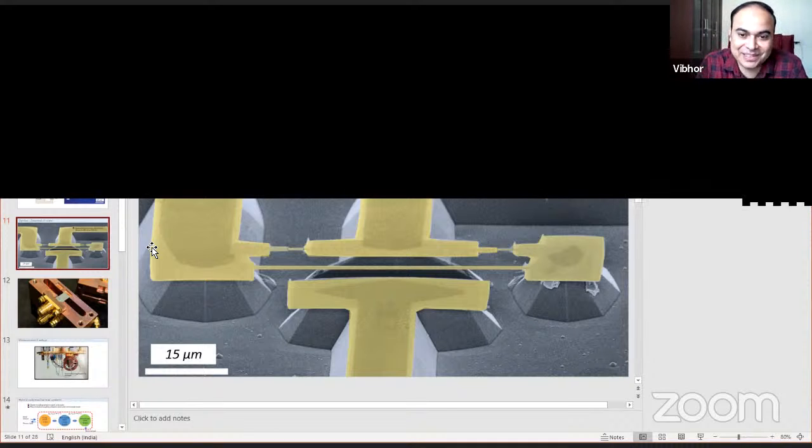So I would expect that suspension is perhaps not causing the loss of coherence. It's the silicon nitride. But might there be other modes, very high frequency modes? Electrical modes should not be there, because electrical modes are something that we can see in simulations very well. Okay, and you're coupling by electric field to your cavity? That is right. And your mechanical mode is sideways, in the plane of the... Yeah, it is in the same plane as the qubit capacitor.